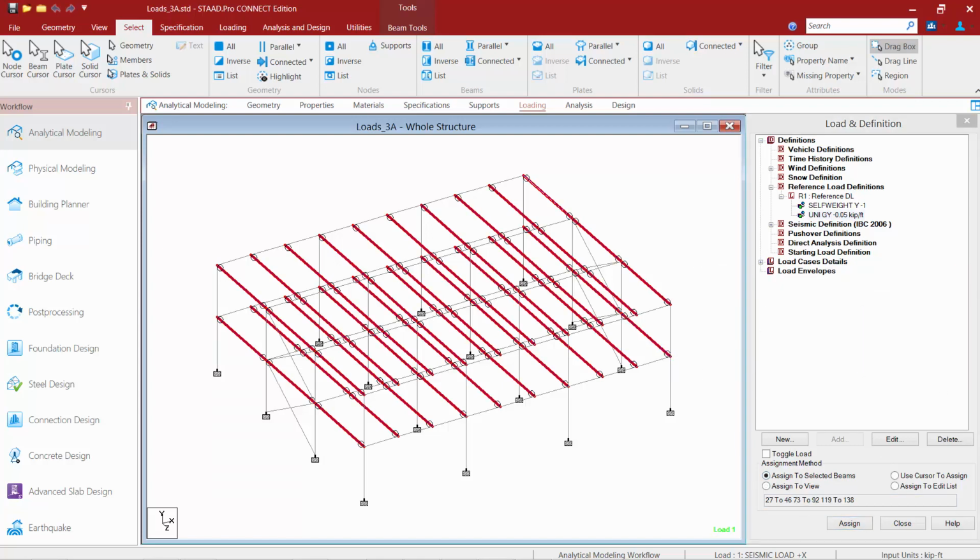Now, what am I going to do with these loads after I create them? Well, again, this load case is not going to be directly analyzed by the program. I have a few options here. I could include it in a seismic definition if these were defining my mass of my structure. I could use a reference load case for a time history or a response spectrum analysis.